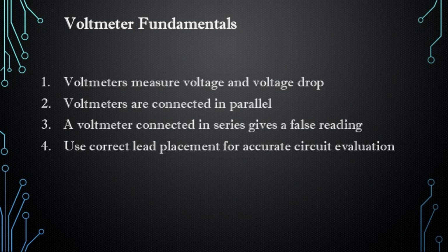Lead placement also matters. The reading only has value when the technician understands exactly what 2 points are being compared. So at this stage, the student has to move beyond just turning the meter on. He has to start thinking in terms of circuit position and test purpose. That is where meter use starts becoming real analysis, not just meter handling.